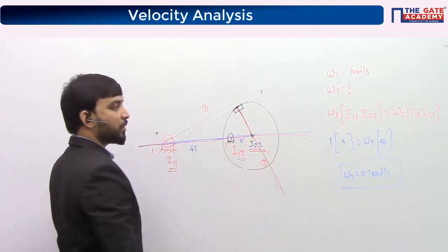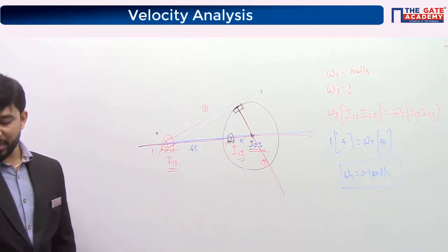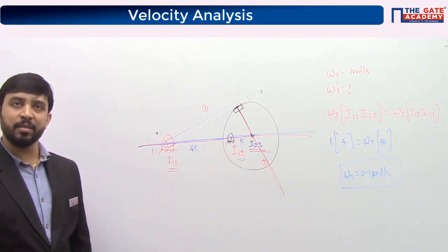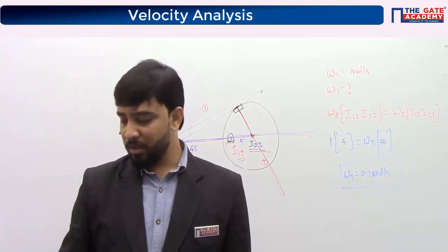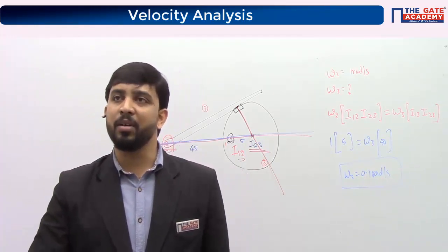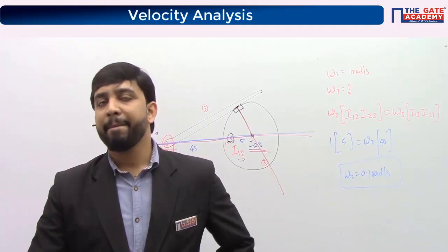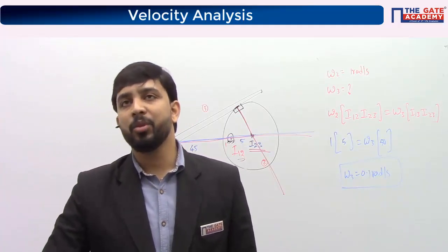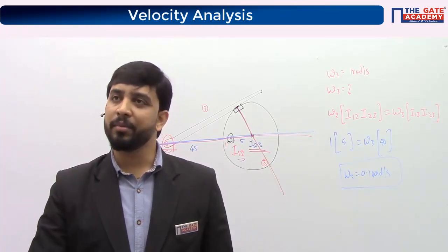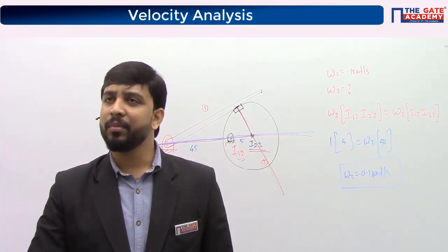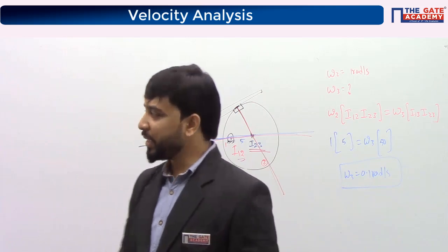So I23 lies here. Whenever you are given just three links inside the mechanism, try to locate it with the help of Aronhold-Kennedy's theorem, okay? You cannot use any polygon method here. So go according to the theorem, okay? So the normal cuts the center, okay?